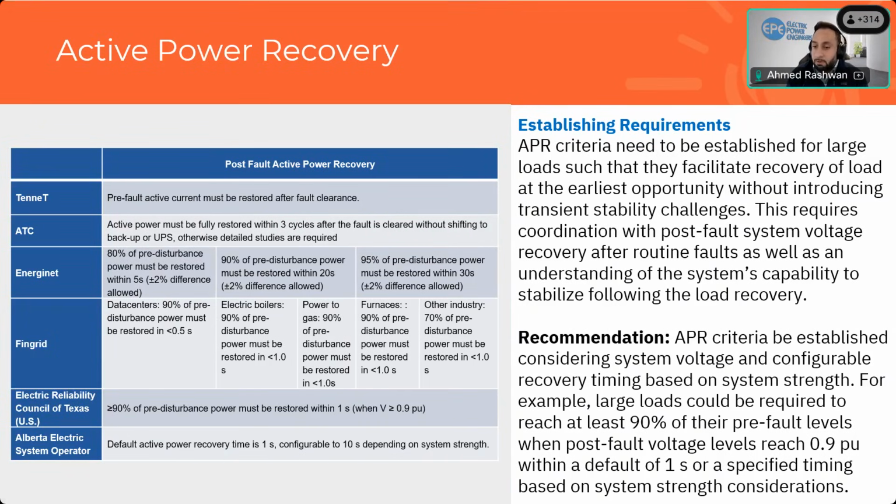So for example, if you're in a stronger part of the system, once you reach 90% of the pre-fault load level, restore back to 90% of the load within 1 second. However, if you are in a weaker part of the system, it may be prudent to extend that time period to being over several seconds to make sure the system remains stable as you recover that load. These are really large facilities, so it's really important to ensure that they don't come back in really quickly and further undampen the transient response.